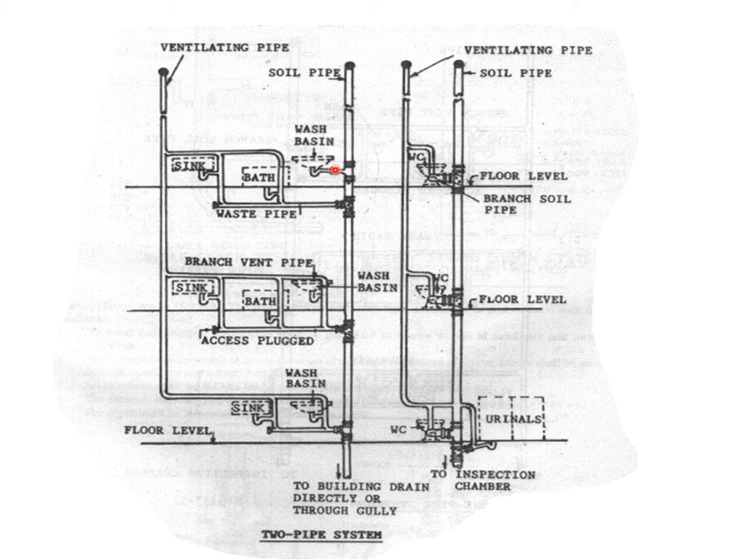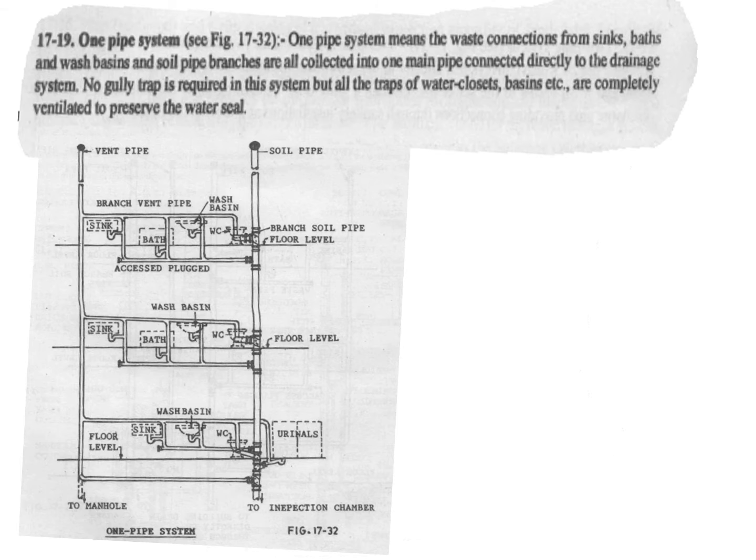The soil pipe will take the waste from the water closets as well as the kitchen basins, then to the main sewage lines. To avoid air locks or water hammers, we can provide ventilation pipes separately from the soil pipes. This is what is called the two pipe system.